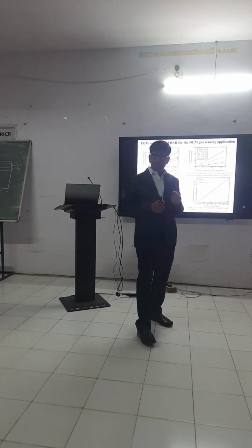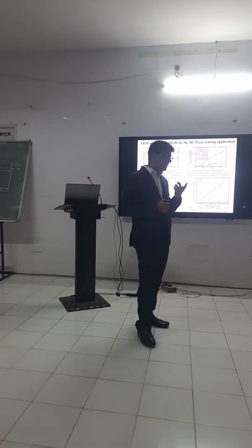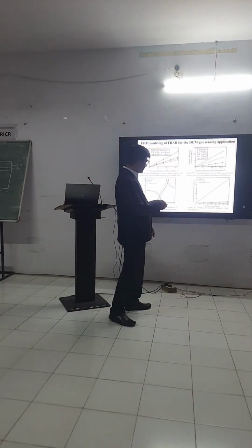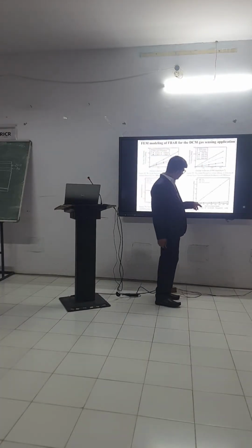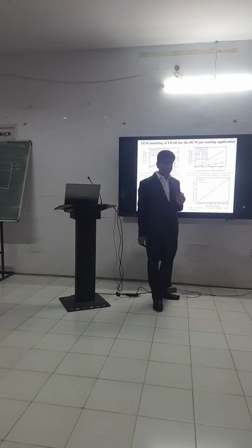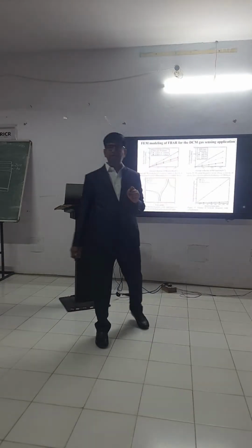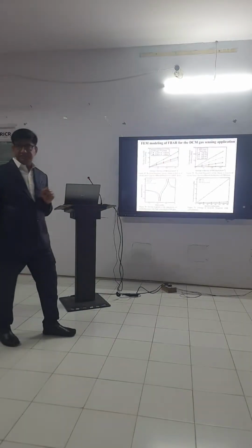So what we need to check? We need to check the selectivity of my sensor also. So here you can see the selectivity response. It is very sensitive, or selective, to only DCM, and for other gases it will work as noise. It will be created as a noise. Clear? So that's how we have to design our sensor.